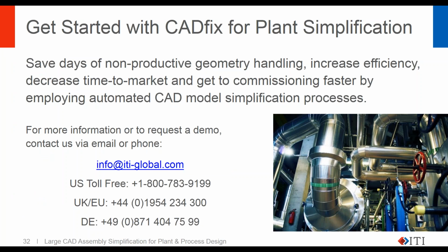Yes, we do. What I've been showing here largely today was a subset of the CADFix functionality, because we've found that to go after the process plant market, where people are just really worried about the file size, they don't want to get too caught up with the detail of repairing CAD models. So we're looking at a simplified, streamlined interface. But the core CADFix product itself is a much more comprehensive system with full repair capability for surface models, solid models, where we can turn surface models into solids. We can do the handling of faceted models, reverse engineering. So the full product is much more extensive than what I've shown here.